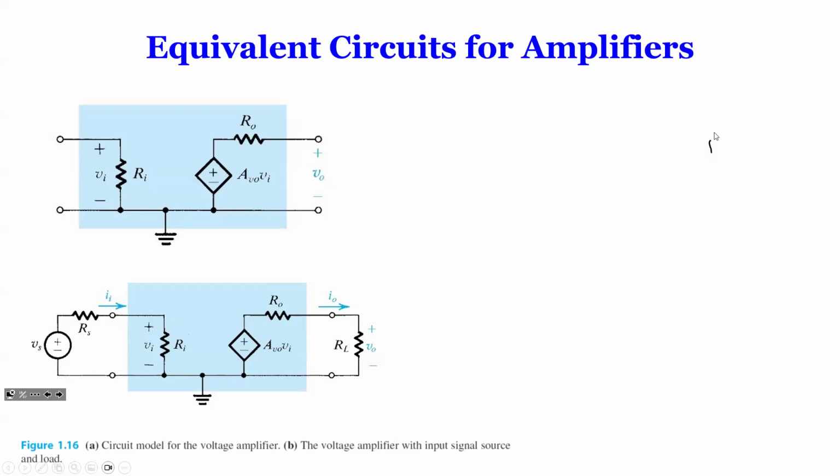It's good. Now, if this is still 10K, but this, for some reason, has an output resistance of, say, 10 mega ohm, what happens now? Whatever, let's say this is 5 volts, you get like 4.9999 here, only 0.0001 here, right? So that's not going to work. That gives you the conclusion that the smaller the output resistance, the better.